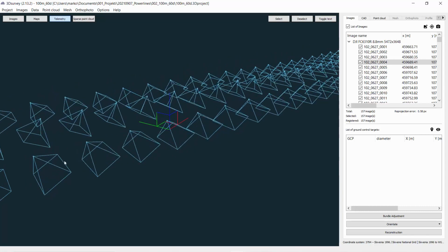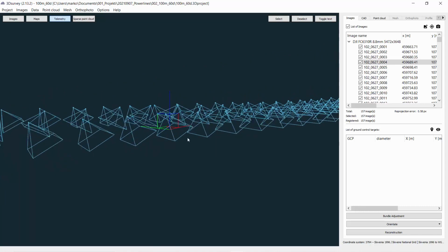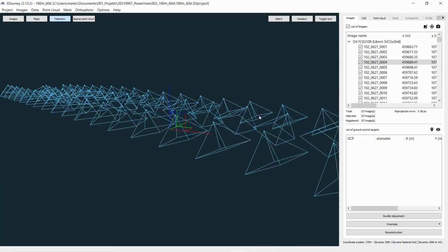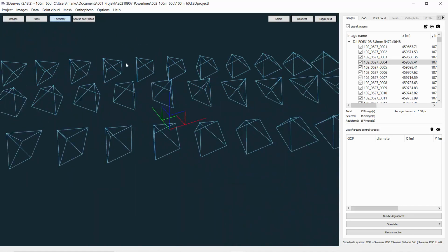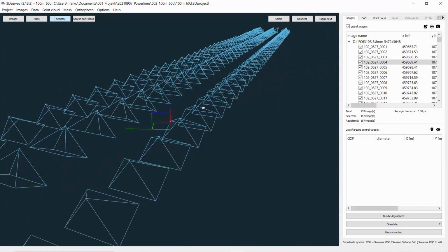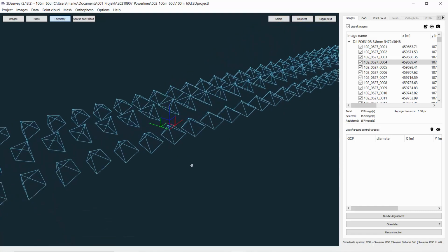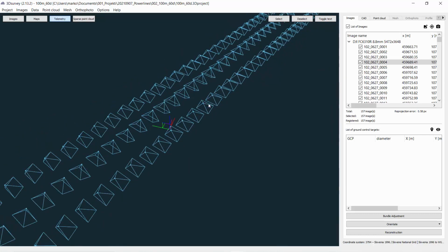We see the drone was flying here in front, the camera is pointing a bit forward, once again 60 degrees, and when it flies back it looks the other way, and then again back. This is still not too much, and all images, from the first line, and when it flies back, the second line, the camera is pointing in the other direction, but not too much, and all the images are able to successfully match together.